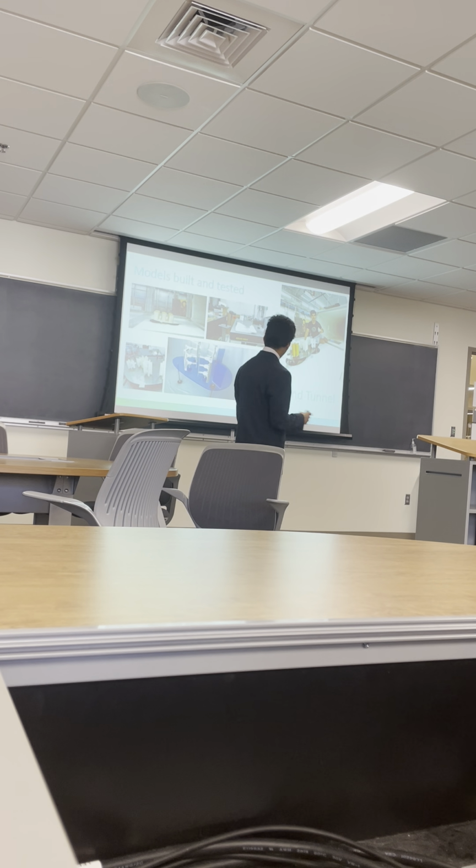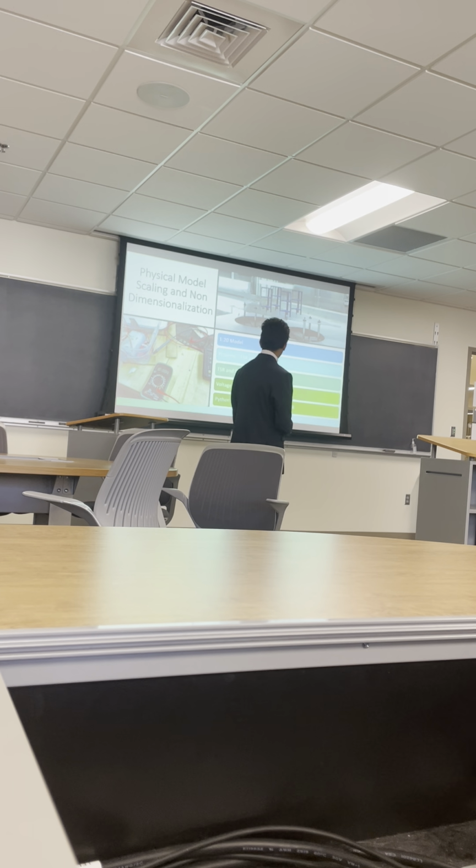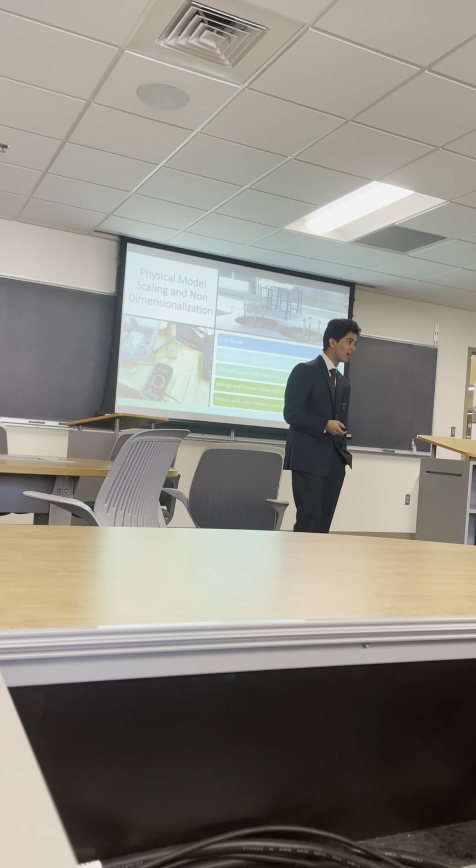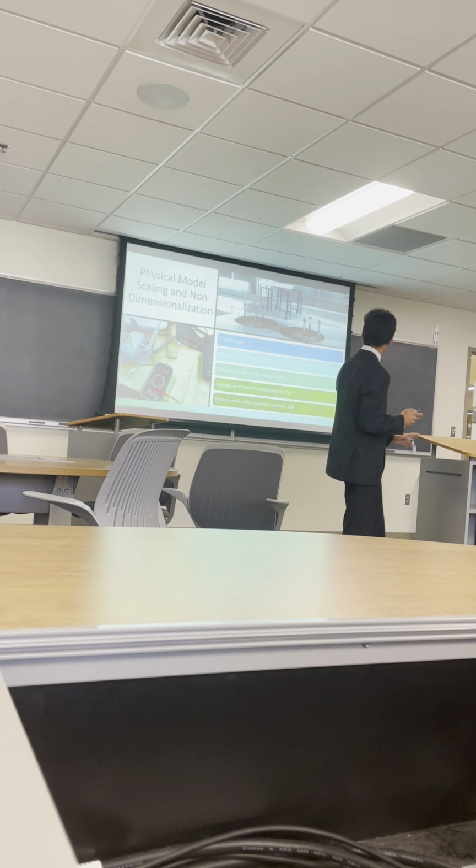I also did wind tunnel testing. I constructed over 8 different models, more in the picture book, to verify my designs, along with 4 turbine, I tested 6 and 8 turbine models. And the final model was a 1:20 model with the pi terms from the Buckingham Pi principle, TSR, and CP. I used voltage and current for measuring CP and tip speed ratio to measure TSR.